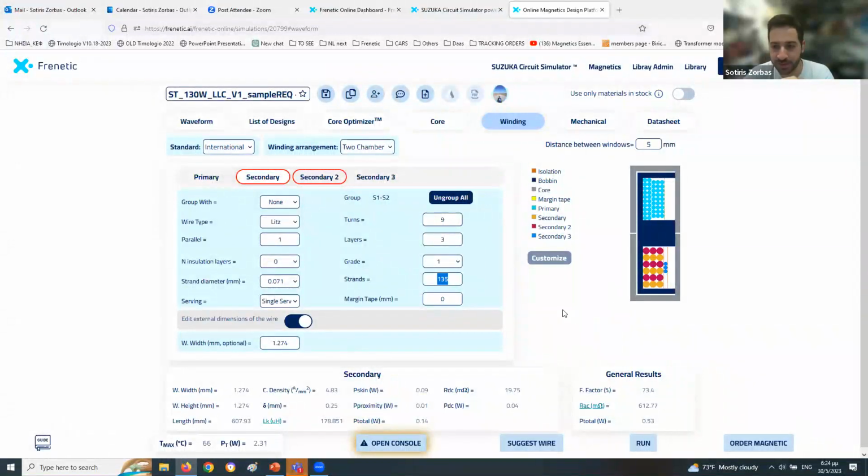And the auxiliary winding right here. Grouping is important because it's going to make the leakage inductances of the windings be as close as possible. Even 10%, we can tolerate 10% difference in the circuitry, no problem. But usually it's better than that. And always, not only the leakage inductances, I mean, the actual inductances of those windings should be matched because in a center tap topology, we have to match those things.